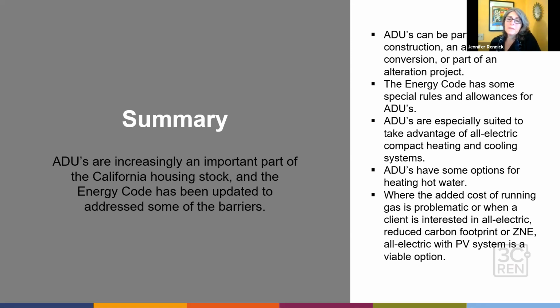And I think you want to keep in mind that ADUs are part of that new construction. That's probably the first thing you want to really sort out when you're looking at that. Is it standalone new construction? Okay, one thing. And then if it's a conversion of any type of an existing structure, whether interior to it or outside of it, detached or attached, then you're going to be falling under the part of the code that's specific to additions and alterations.